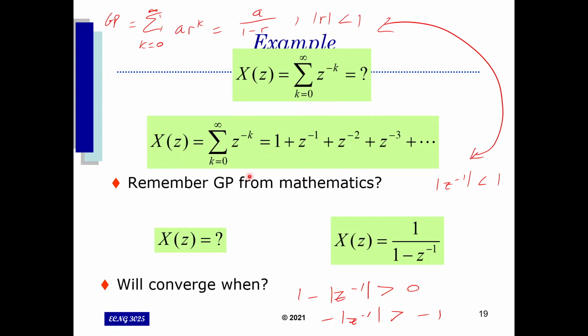Once we had our equation, we just let the denominator be more than 0 and calculate our region of convergence for our Z component. The only thing to pay attention to is that if we had negative signs on both sides, or if we were changing the signs on either one of these sides, the inequality sign will also change as a result. So this more than here changed to a less than as a result.